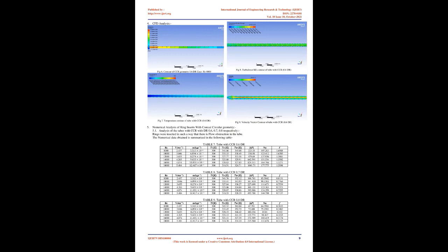The wall of the pipe was assumed to be perfectly smooth with zero roughness height, stationary wall, and no slip condition. Initial outlet gauge pressure was taken as 0 Pascal. Temperature was taken as 300 K. Constant heat flux of 1500 W/m² on the outer surface of the horizontal tube is applied. Velocity inlet boundary was taken for the pipe inlet section, and the velocity values for the different Reynolds numbers are given in Table 3. Velocity for different Reynolds number.